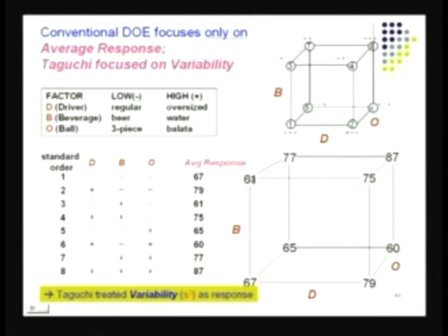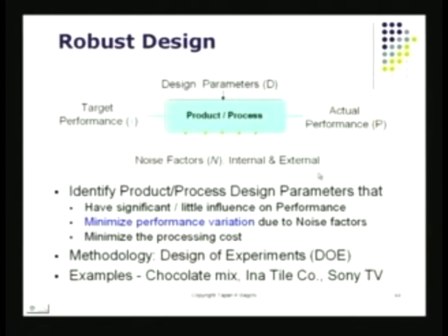So when I've got this experiment running there, take a look at what is the impact of the different factor settings on S square there. So I measured S square all around. So not only am I trying to look at the effect of the different factors on average response, but also I'll be looking at the variance of that response. This is the idea that was exploited when Taguchi came up with a scheme to develop robust design.